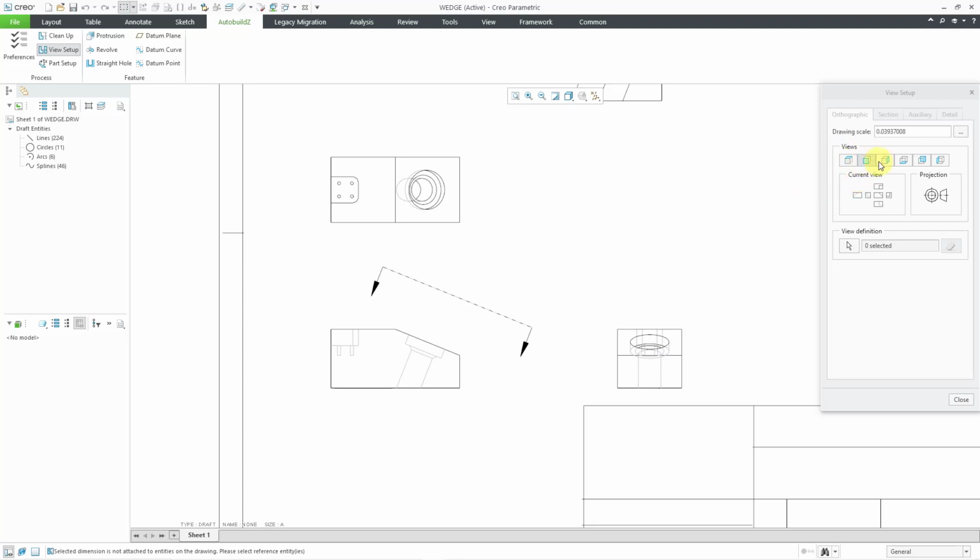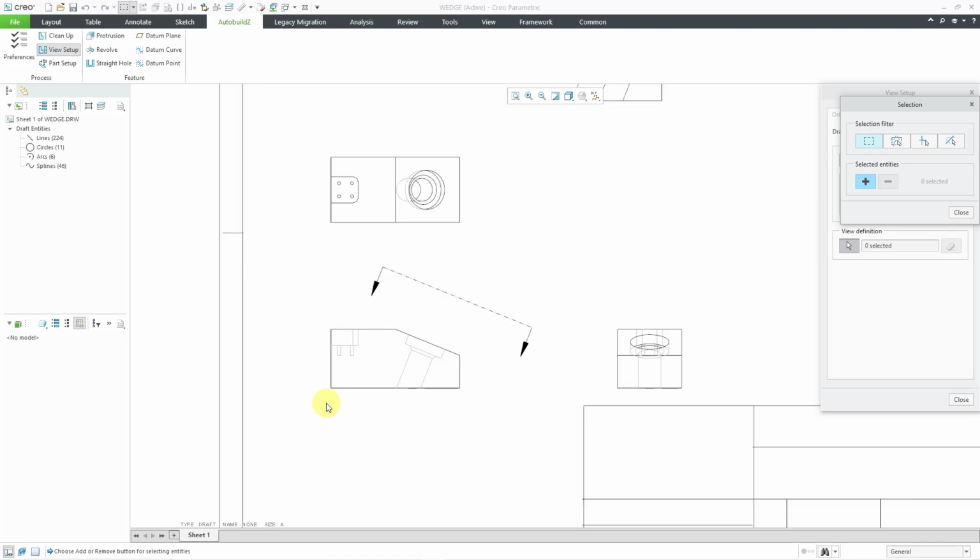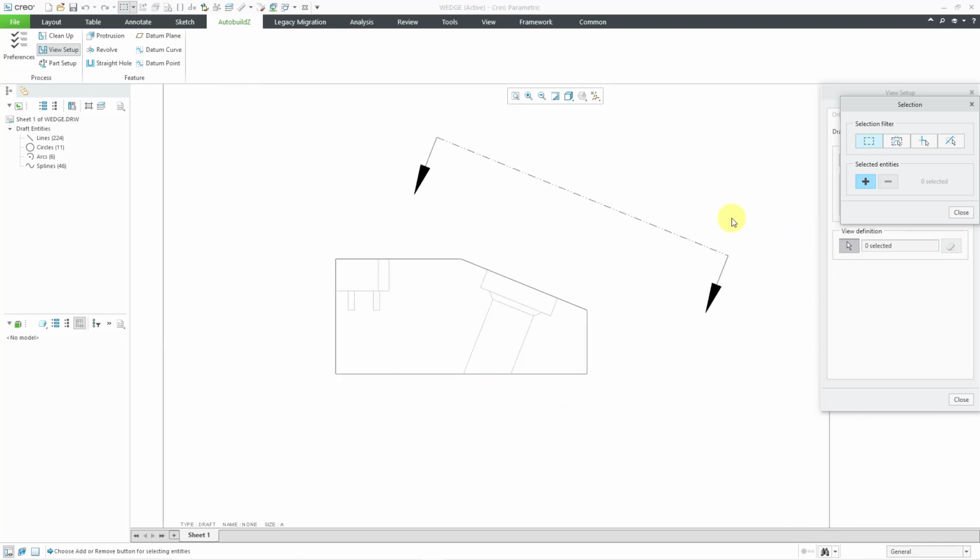And so it gives you the standard 6 views up at the top. Here we have the front view. You can also configure if there's a top view, a right view, bottom view, back view, and left view. But the front view is selected. I can use the pick icon to select what is supposed to be in that front view. So let me zoom in a little bit.